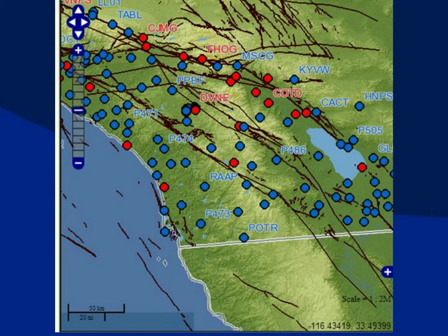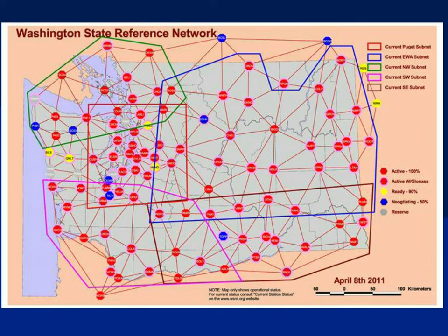So I guess the question might be, how far away from the base could I be? Well, your accuracy degrades with distance from the base. That's one consideration, certainly. But I've gone out as far as 20 miles and not had any problems, and I've heard of people going even further than that. So it's a matter of finding the bases closest to you first, and then going from there. But with RTK networks, since these bases are talking to each other, distance to the base is really a non-factor. You just pick the mount point for the region that you're in, and it will optimize the solution based on multiple bases.